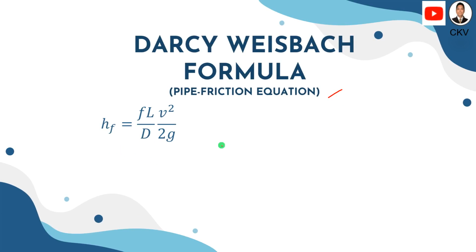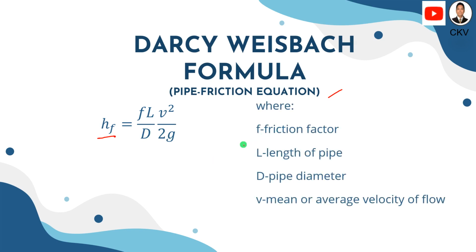So the formula for Darcy-Weisbach in computing the head loss in a pipe is f L V squared over D times 2g, where f is your friction factor, L is the length of pipe, D is the pipe diameter, and V is the mean or average velocity of flow.